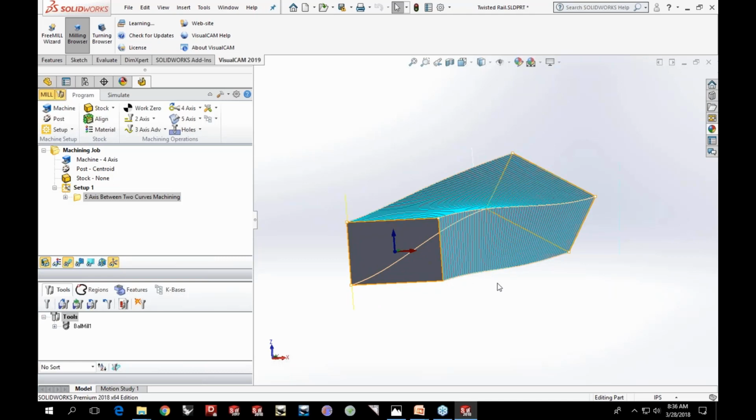And the normal of the tool, even though it's constrained to the two planes that are parallel, or I'm sorry, normal to the rotary axis, can vary. It can vary in both two directions, that is. So that's why he's calling it a true four-axis as opposed to a wrap four-axis, where you only have, in reality, just three axes moving, X, Y, and a rotary axis. Here you can have X, Y, Z and a rotary axis moving at the same time. I hope that makes sense.